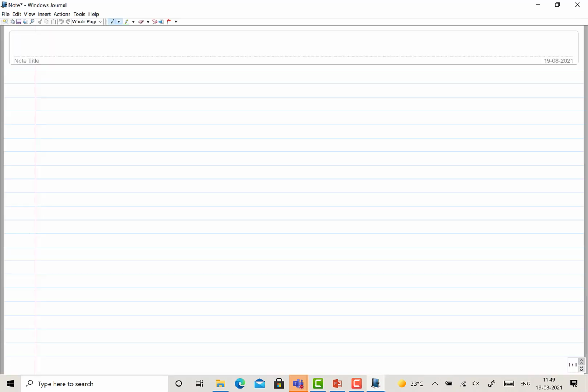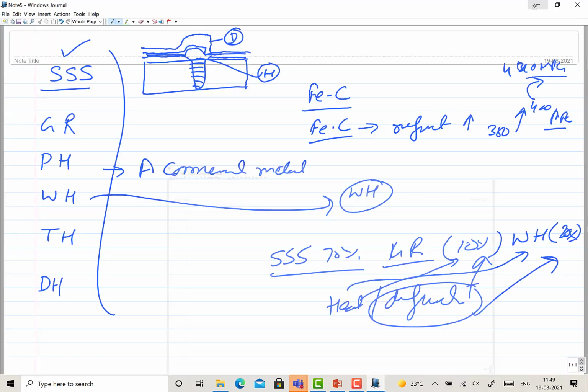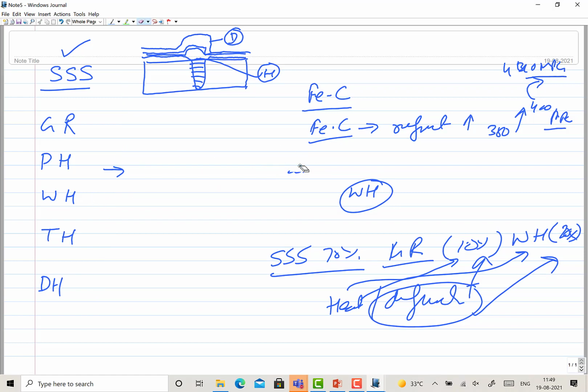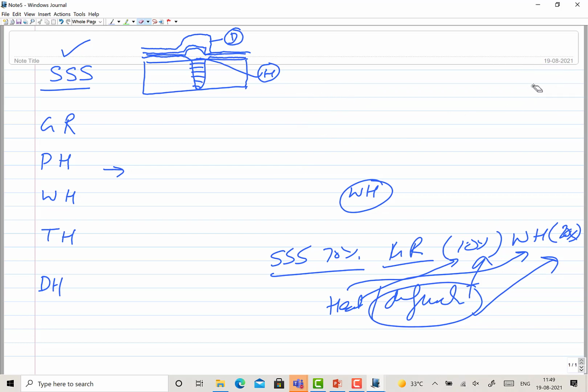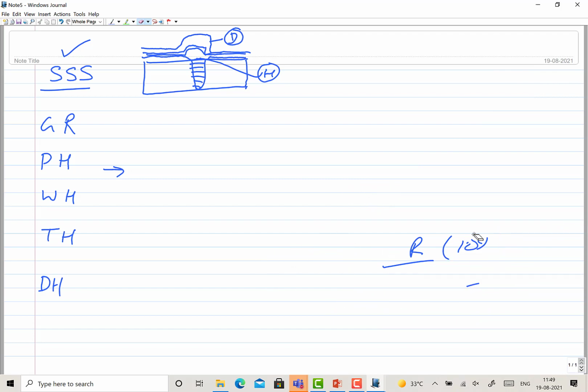So the point here is the relative importance of the things can change significantly. Relative importance of which mechanism is contributing how much, and how much heat is being generated and the deformation is being induced during the solid state processes, that will be determining the performance of the joint eventually.